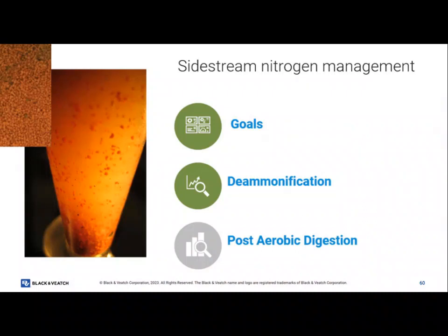So if normally you're getting denitrification, let's say your nitrate going out is usually 9 milligrams per liter. You're getting some denitrification. So coming in, maybe I had 25 ammonia. This is in, out, fully nitrified, and that's all nitrate. If I'm managing that, I'm getting my BioP to work, but then I increase this by 20%, so we increase this to 30 milligrams per liter.